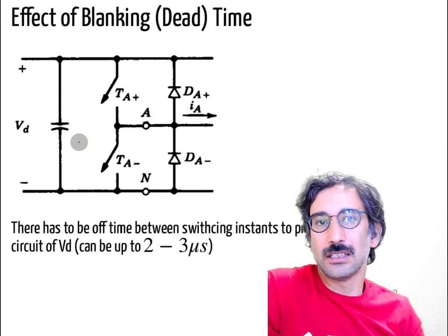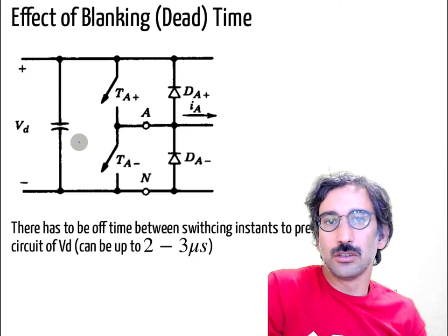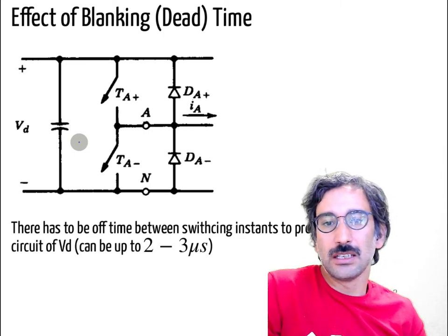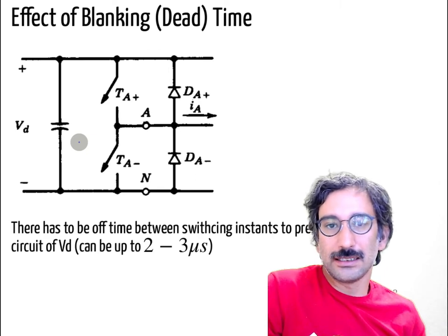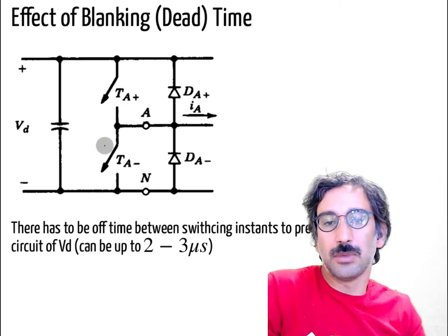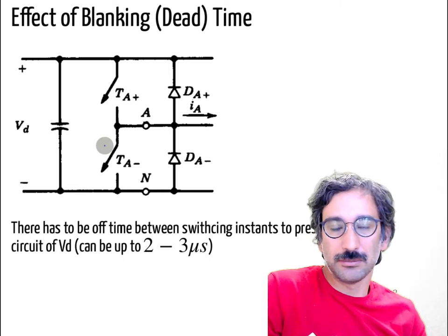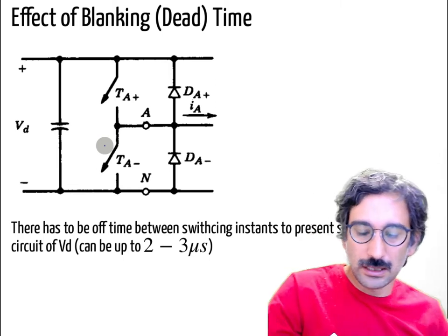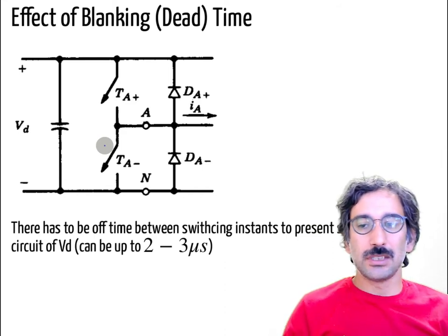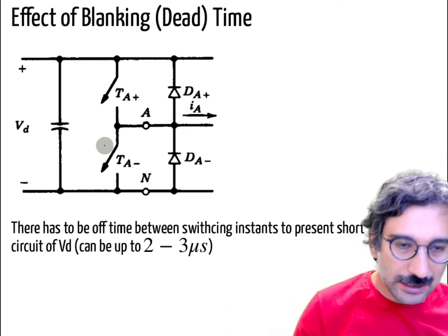Because there is a non-zero turn off time for transistors. So if we ignore that, we can still damage our transistor by short circuiting the top and bottom switches.